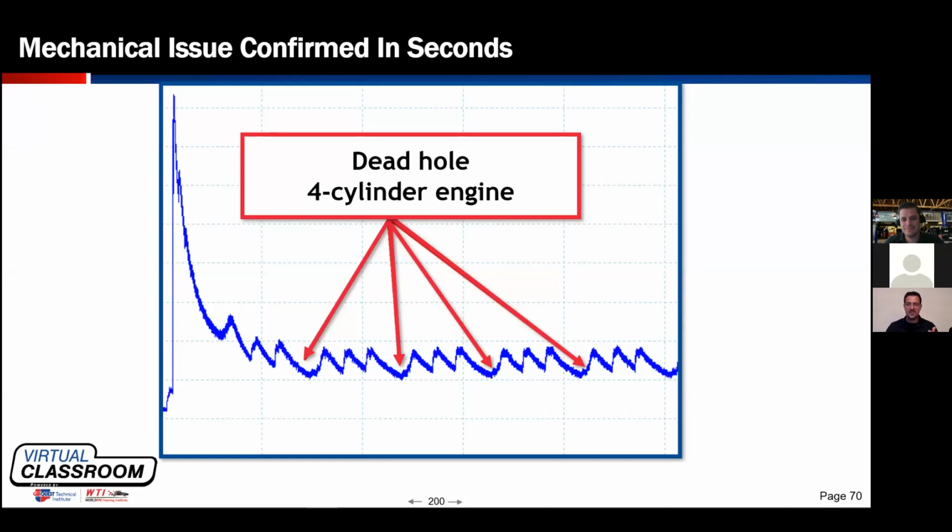So doesn't it make sense that if I pull the car in my bay, maybe I heard this out in the parking lot, da-da-da-da, and I know I've got an engine mechanical fault. I'm going to put my amp probe on there, and then I'm going to add a second channel. And adding that second channel doesn't really mean anything until you know what. I might add an ignition sync. Maybe I know it's on cylinder number 1. Exactly. I need to know the firing order.